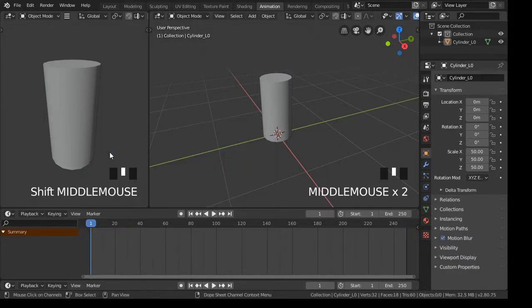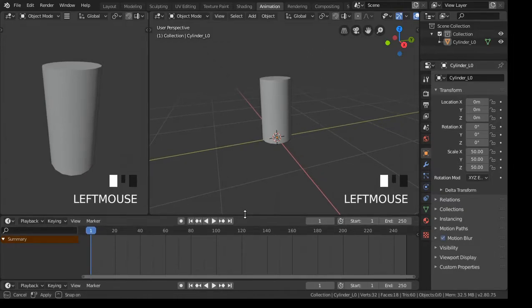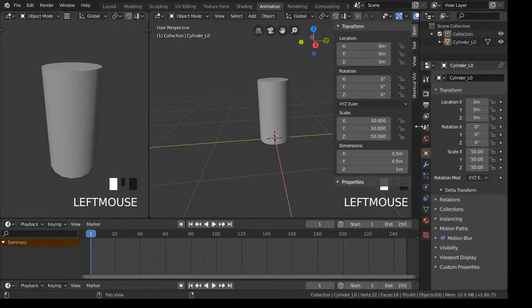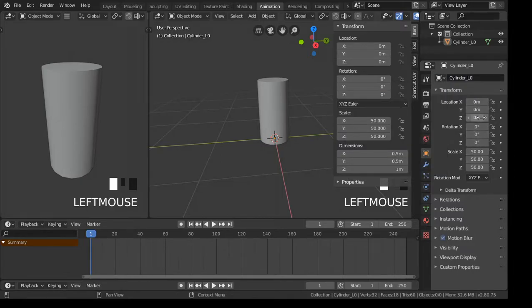If you don't use the timeline, then you will have problems with exporting. So make sure you are in the timeline and not the dope sheet. We don't want to do any dope editing for animation in TMTK. It's timeline specific. So there are two ways that you can animate. One, you can use your hotkey I to apply your rotations and locations here in the item menu. Or with the item selected that you're working on, you could do it here.